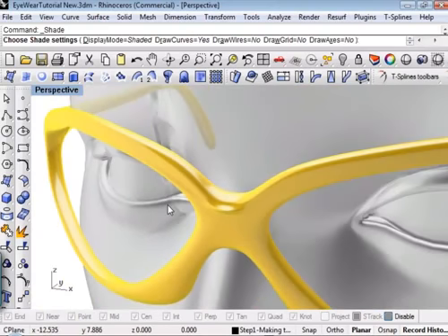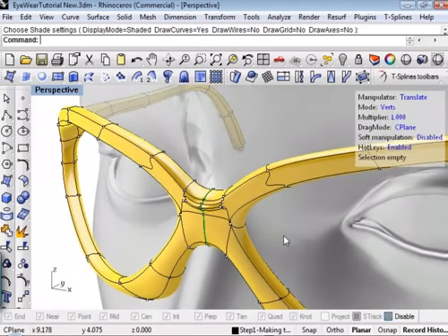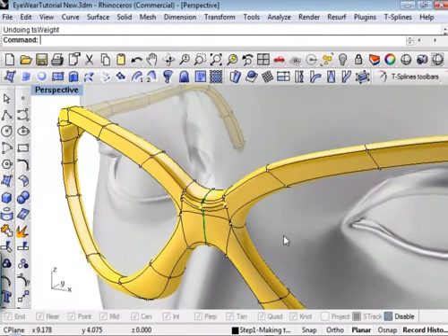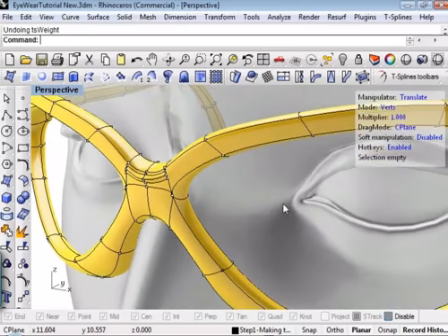The other thing about this is if you avoid knife blade situations, your models are going to look better when they're rendered, because one of the biggest tells for a CG model is edges without fillets on them. It just makes them look too crisp and too hard, and it's one of the things that make your models look CG. So I tend to like using weight, insert edge, and add weight and stuff like that in order to get nice soft edges, and then they render nice and they look more realistic actually.